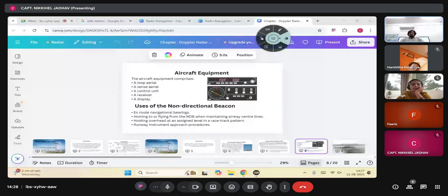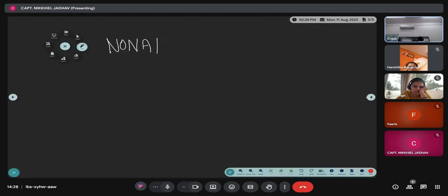Okay. Then there are the signals of this ADF. I think this presentation I had done for training the Indigo cadet program, so it's very brief, only what is needed. Let's go back to the CPL syllabus. The signals of this NDB will be of two parts: non-A1A and A1A. Okay, two parts. One part is non, the other part is A1A.